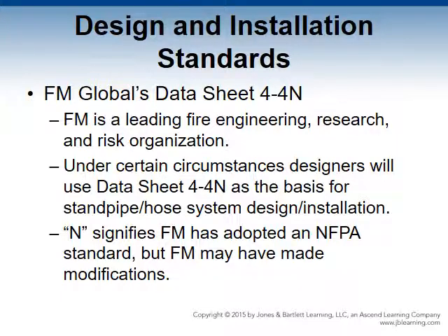In certain circumstances, such as when insurance requires it, design professionals will use datasheet 4-4N as the basis for standpipe and hose system design and installation, especially as designated by the insurance carrier. N signifies that FM has adopted an NFPA standard, but FM may have made some changes before publishing it.